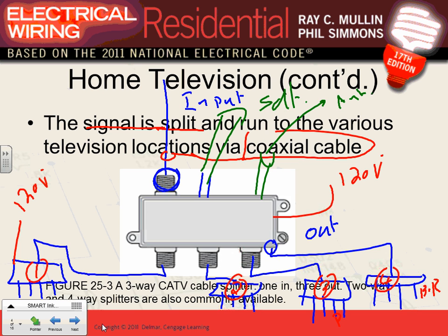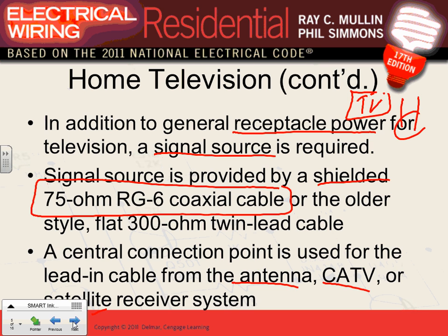So keep in mind, every time you bring a signal, you bring it to that combiner, and then you split it through the whole building. In our project, I'm asking you guys to bring a coaxial cable to the building and split the coaxial cable into every apartment like we've done here. And from every apartment, it's going to have a splitter like this that splits to a certain location based on what I told you. Bedrooms need one. I want one in every bedroom and one in every living room.